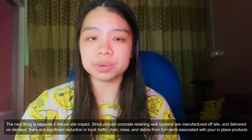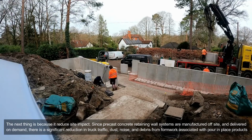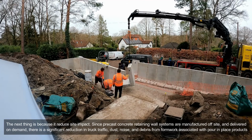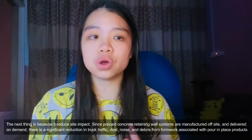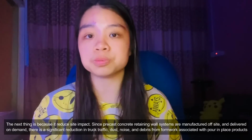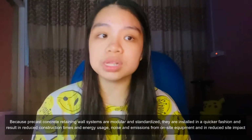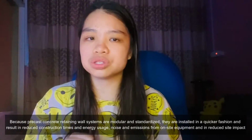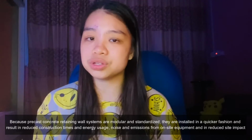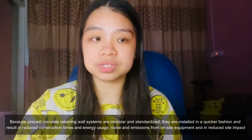The next thing is because it reduces site impact. Since precast concrete retaining wall systems are manufactured off-site and delivered on demand, there is a significant reduction in truck traffic. Thus, noise, and also debris from formwork associated with poured in-place products. Because precast concrete retaining wall systems are modular and standardized, they are installed in a quicker fashion and result in reduced construction times and energy usage, noise and emissions from on-site equipment, and in reduced site impact.